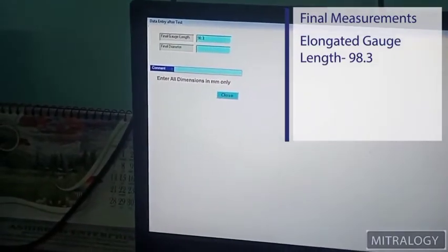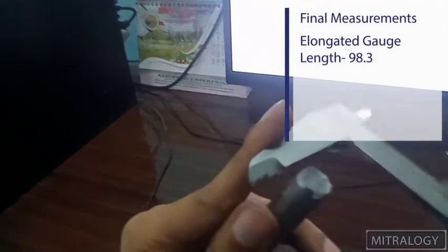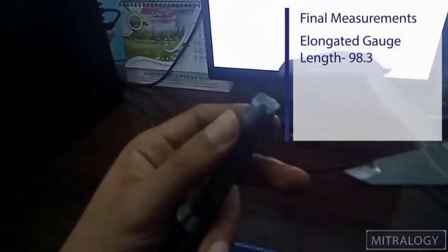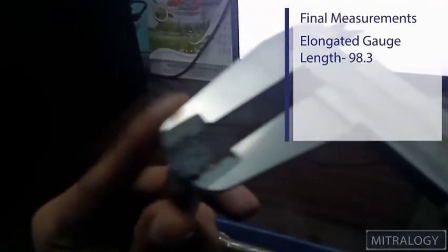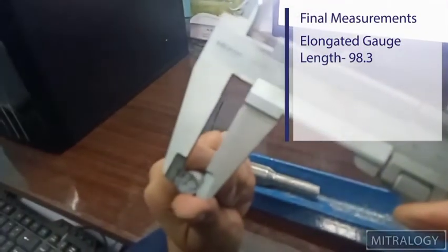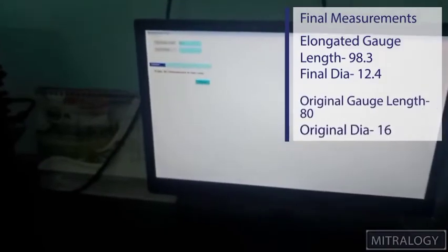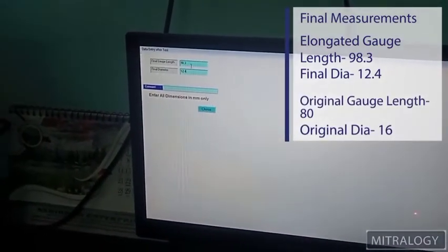Now the final diameter. As I can see, the specimen has a cup and cone shape in the breaking part. This is 12.4. So the diameter reduced to 12.4 from 16.